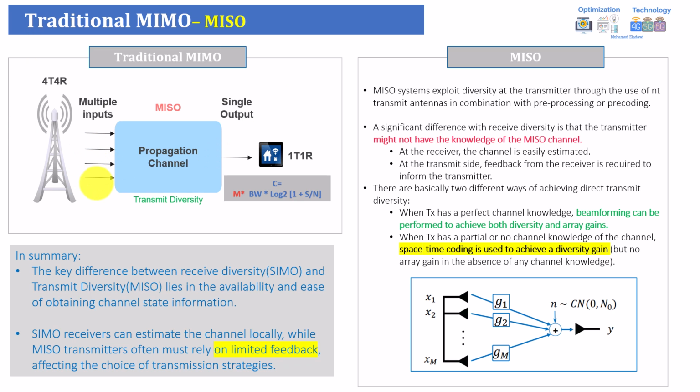So this is like you receive the signal twice. So you will again make sure that one of them for sure will be better than the other. So this is actually at the end will give the gain from the transmit diversity. But again, the receive diversity usually gives better gain because the UE is very aware about the channel propagation all the time. So this actually makes it easier for the receiver to achieve the gain.